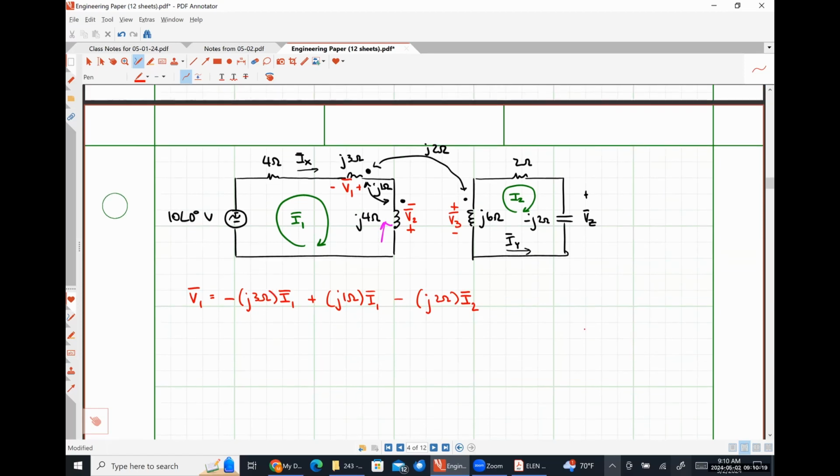So let's explain this stuff. This is why this is tricky. So let's go back through and do this whole thing over, just step by step. When we're looking at our self term, we're looking at coil 1 for both the voltage and the current. Here is my positive polarity terminal of voltage V1. It is on the same side as the dotted terminal. That is true every single time.